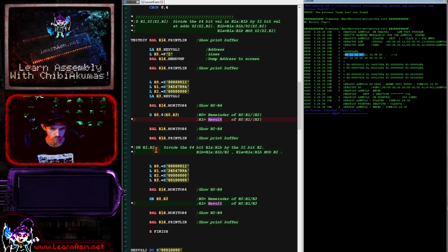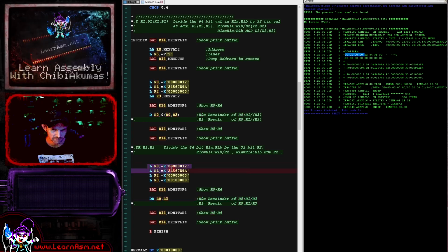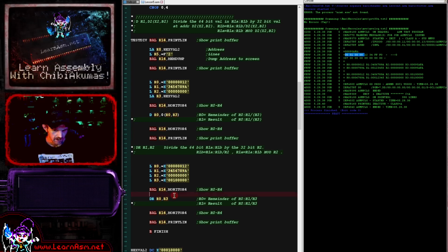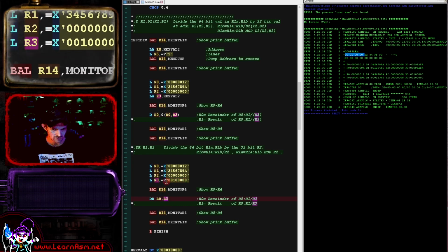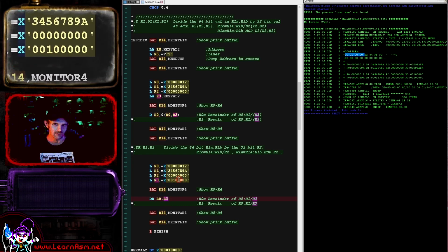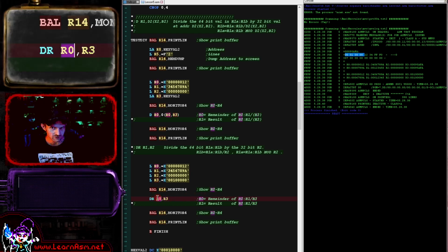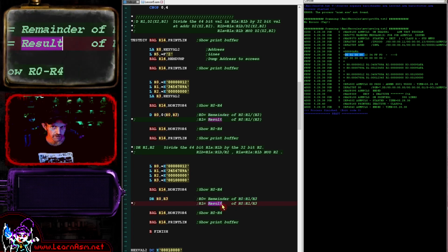We can also work with a pair of registers. So here we're specifying a source register, R0, but once again this is the first of a 64-bit pair. So when we specify this, we're actually specifying R0 and R1 as a 64-bit pair. So again, 1, 2, 3, 4, 5, 6, 7, 8, 9A here. This time though, the second parameter, the 32-bit parameter, is a register. So we've got the same value in the register just here. Actually, that's not the same value. It's got an extra 0, so that's 1 and 5 zeros. So extra bonus 0 there. So we're going to do that, and then again, just like before, the result is in 2 registers. R0 will contain the remainder, and R1 will contain the actual result of the division there.